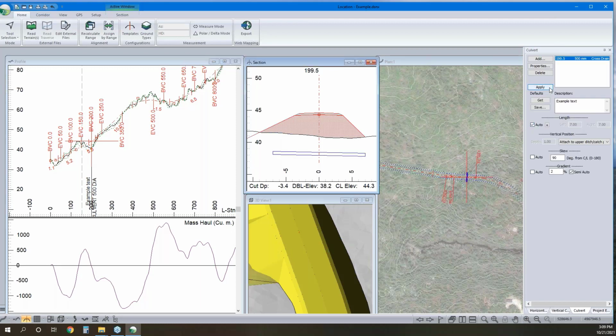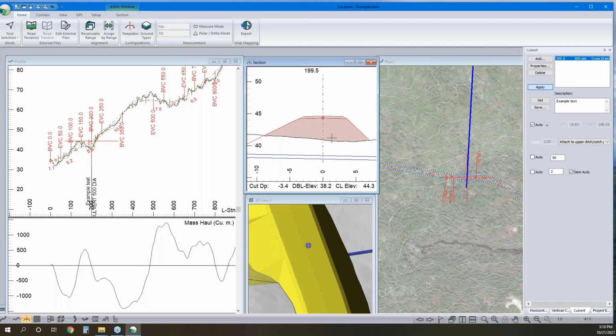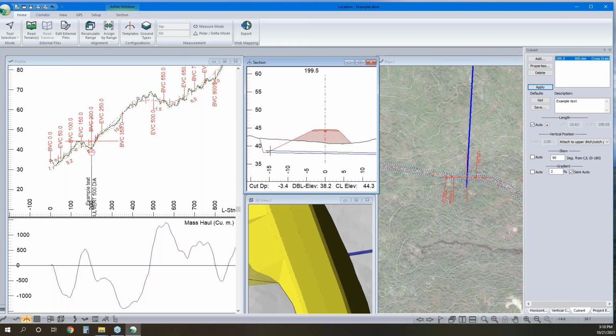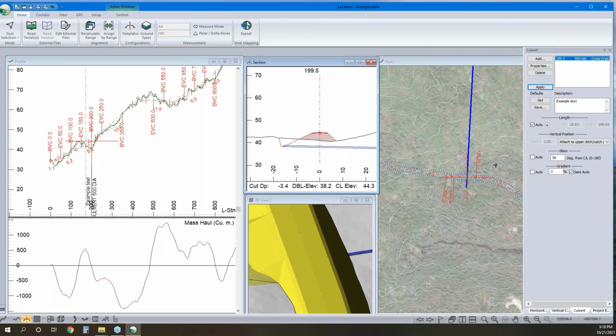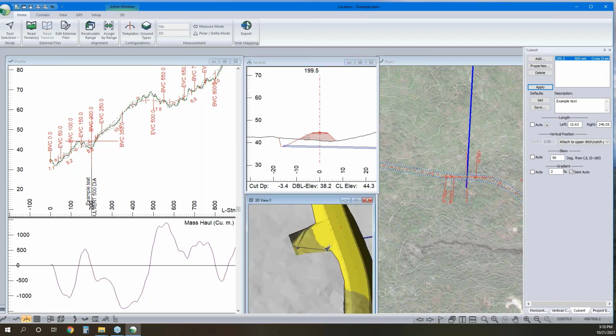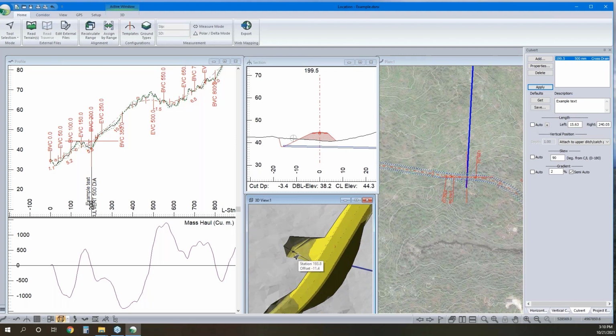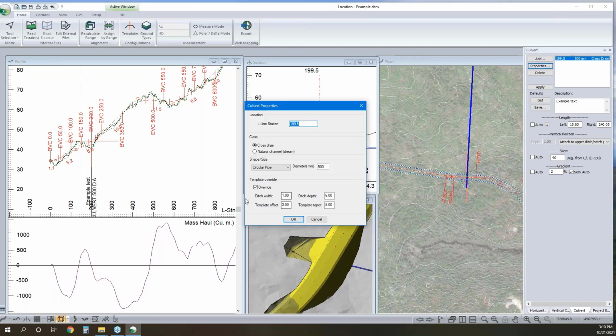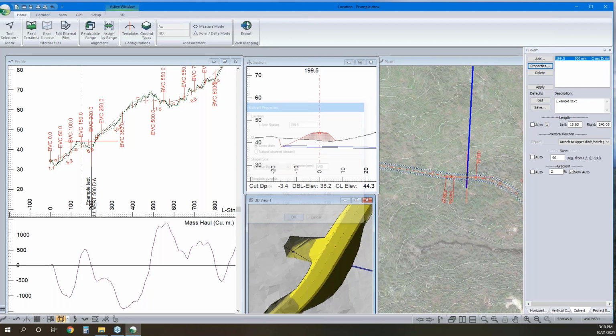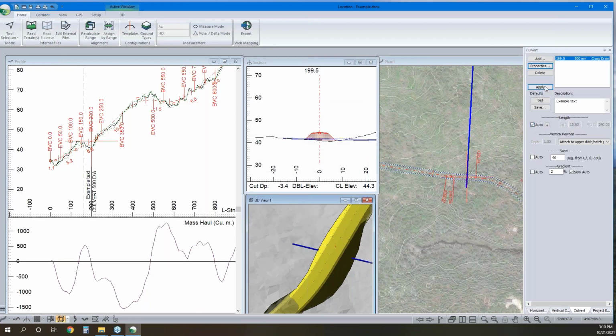So if I set this ditch depth to be, let's call it 6, and I'm going to want to turn auto on here. But that deepens the ditch at a specific location for the inlet. Now here, that pipe is never going to be able to daylight, so it extends on, and we'd want to fix it. We wouldn't want a big sump in that location because it's not going to work with the geometry of the site. But yeah, it's a useful tool, and you can include it or exclude it. So here, if I don't want any overrides for a sump, I can just turn that off.